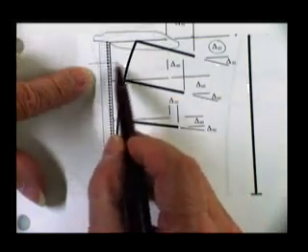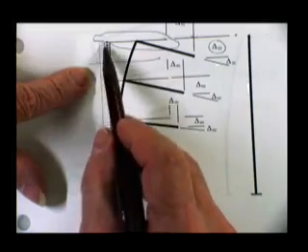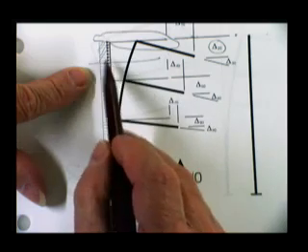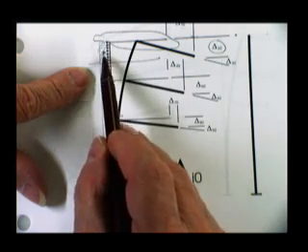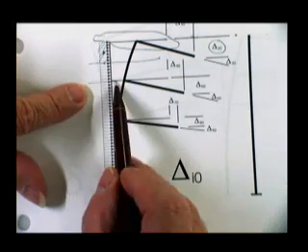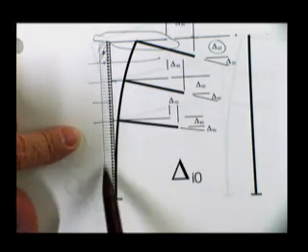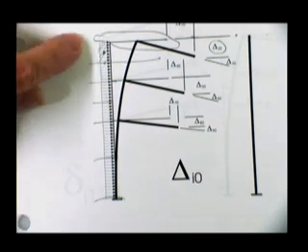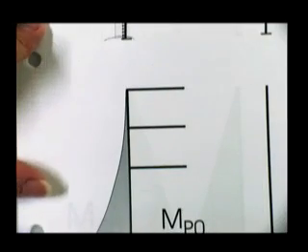His moment diagram halfway up is equal to the area under the curve times a half of a floor's height times the distance from the centroid to that point. His moment here, his moment here, his moment here. You probably won't do that many of them. First thing you say, okay, it's a function of x squared. And so it's a parabola.